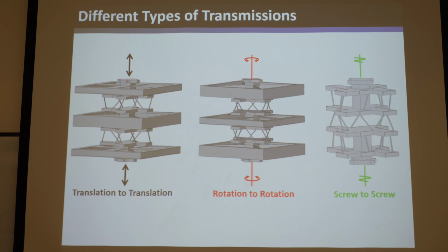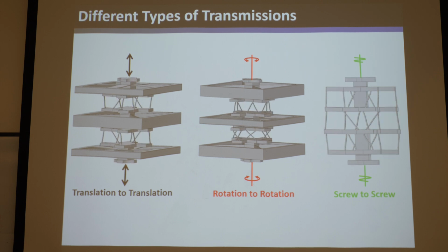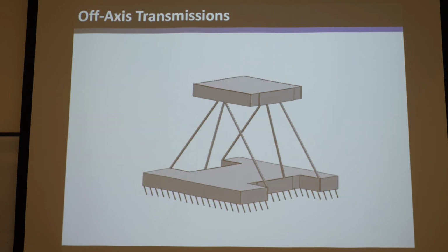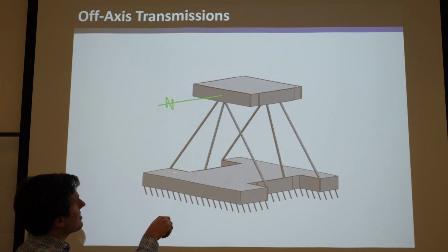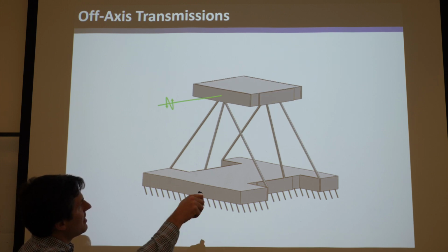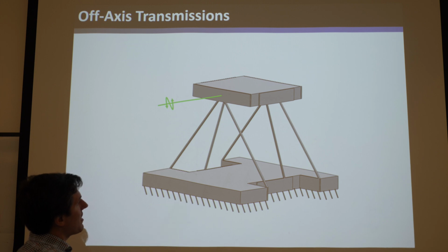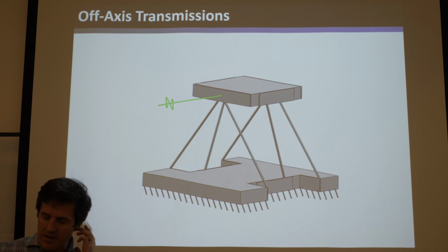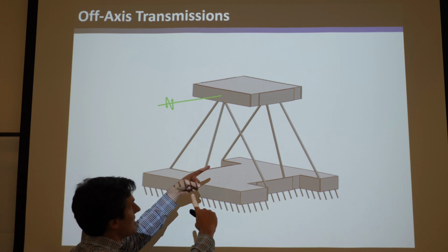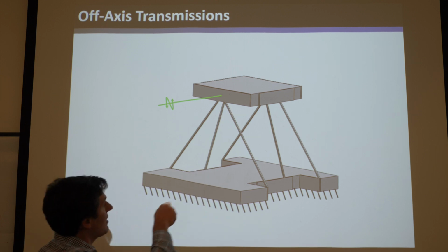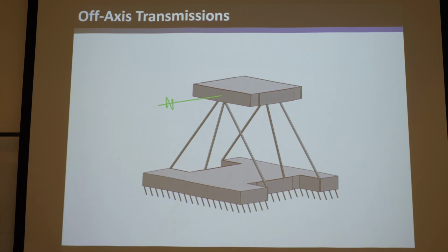Oh, by the way, here's the side view of this, showing how clean everything is. Okay? So remember this flexure that essentially achieved a screw motion. We've added some extra constraints. You can see here's the original, these angled ones, and then here's the side crossbar. We added another side crossbar on the other side just to make it more symmetric. You'll remember when we had the flexure kits, we built this with 5 constraints. Here we've added a 6th angled constraint on the other side that's angled the same way, same distance, so we get a nice screw that's a little more symmetric, right?